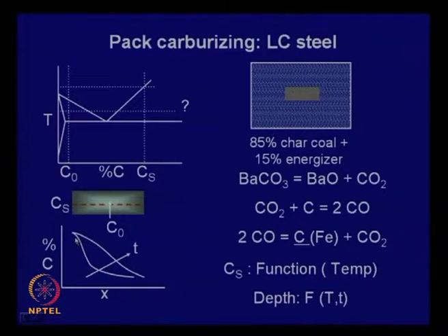So, you will have this kind of a plot, and if you hold it for a longer time at the same temperature, the carbon content at the surface will remain the same, but the depth of hardening, the depth to which the carbon concentration increases, will increase. Like here this is the depth, whereas here this is the depth.